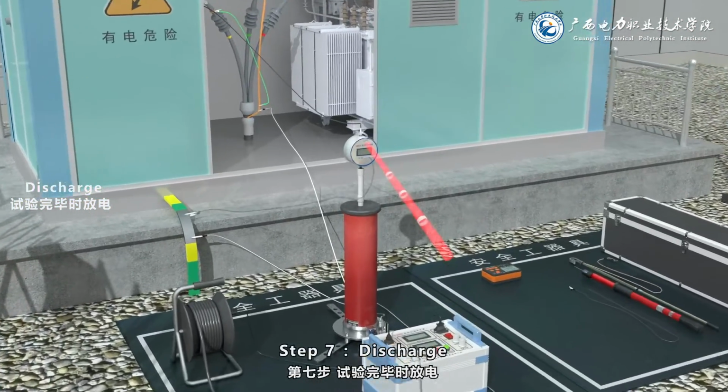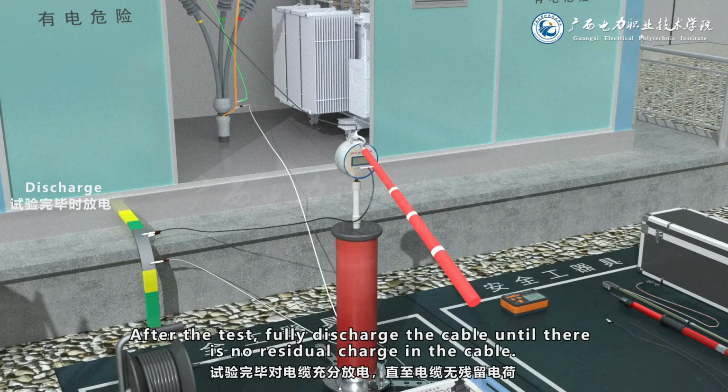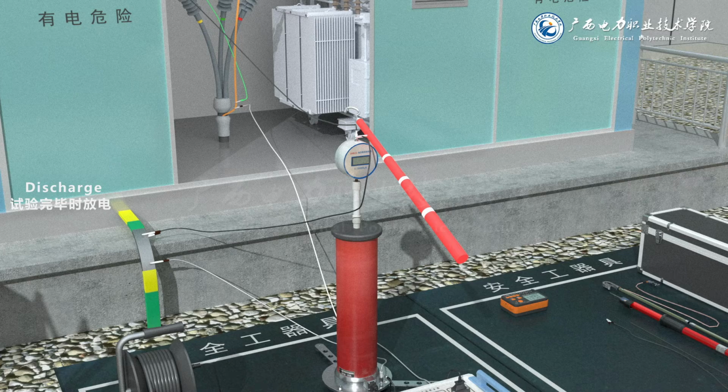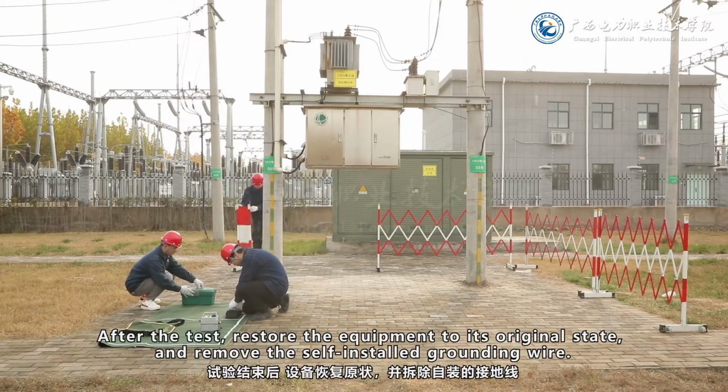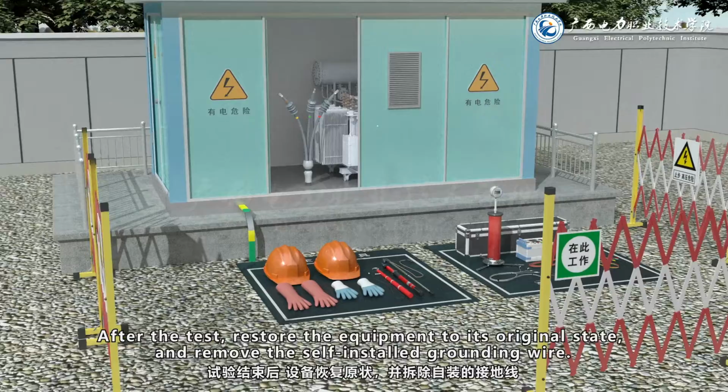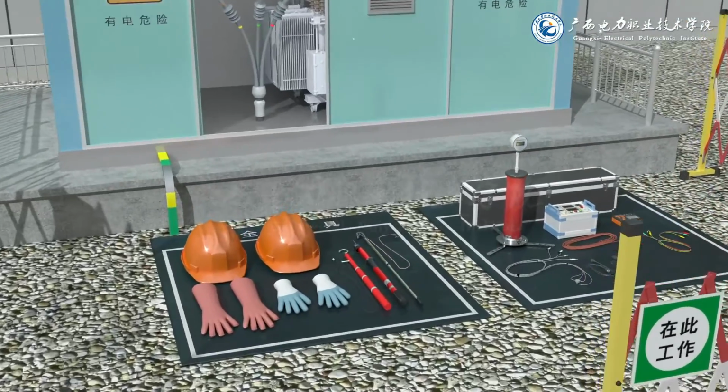Step 7. Discharge. After the test, fully discharge the cable until there is no residual charge in the cable. After the test, restore the equipment to its original state and remove the self-installed grounding wire.